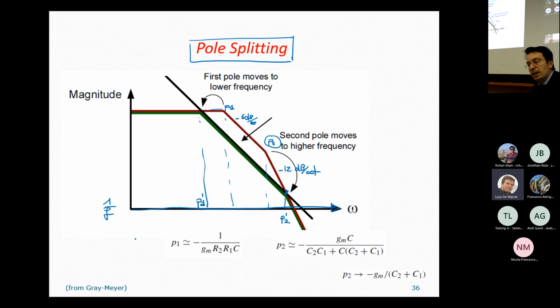To take this into account, we can consider the fact that the VSD of transistor 3 is also equal to the VSG of the same transistor, because this transistor has a diode connection. And the VSD of transistor 4, which should be equal to this quantity, is also equal to the VSG of transistor 6.